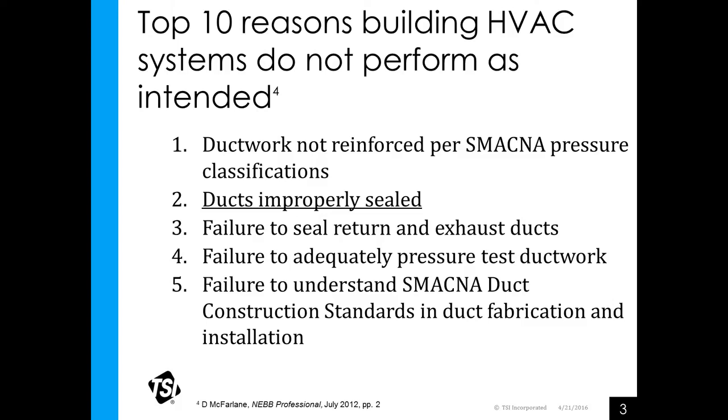Number four, again, time constraints. People look at a commercial application and sometimes they just fail to adequately pressure test the ductwork. I think there was a recent study done in the middle of last year. I'll have to find the reference for it. But it was found that roughly 50+% of commercial HVAC systems have more than a 30% by volume leak within the system. So that's just money down the drain.